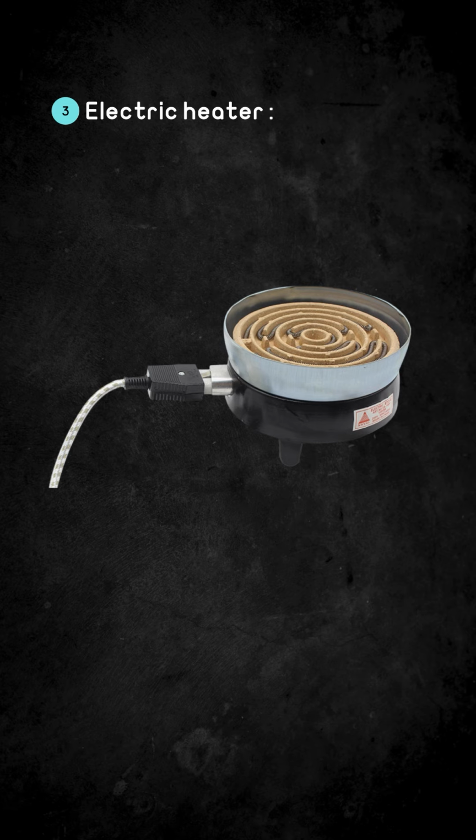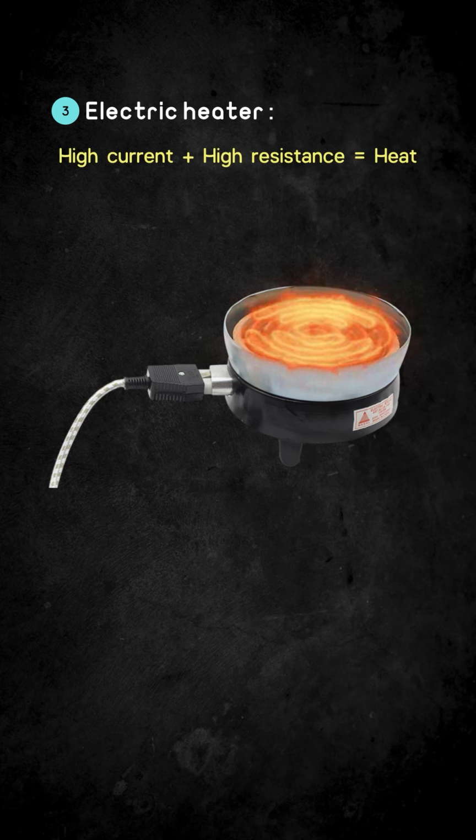In heaters, the final desired product is heat, unlike transmission in electricity companies, where the heat in the wires is waste or wasted energy. But in the case of the heater, the final desire is to obtain this heat. So now we do the opposite. We raise the current and then we place a material with very high resistance. This way, heat is produced for us from electricity. Of course, this heat is undesirable in the conducting wire. So to reduce its resistance, we increase the thickness of this conducting wire.